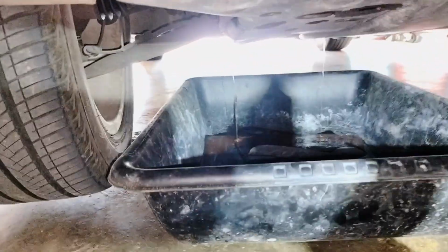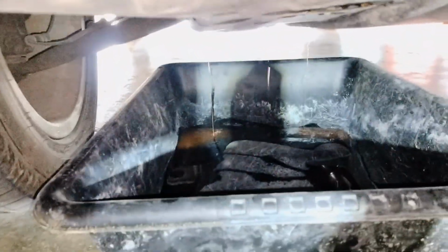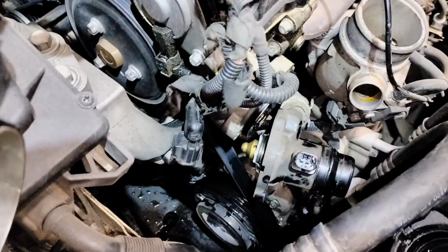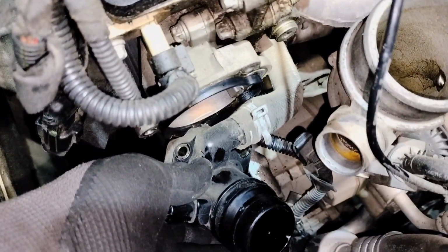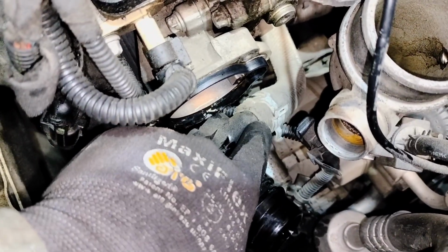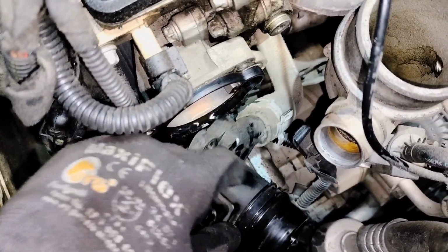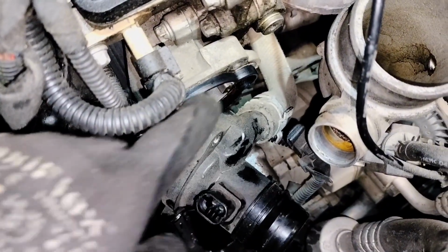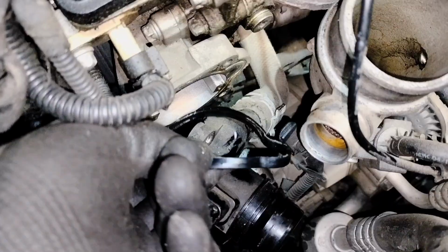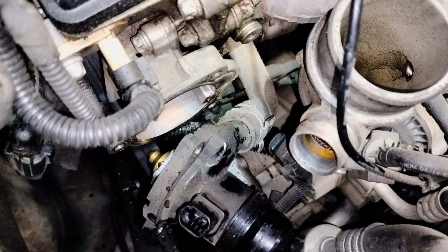So you definitely want a catch pan, because for example this one is catching a lot of coolant on the bottom. So now that I have it removed from the place, I'm gonna have to use pliers to remove that clamp. And I'm gonna just remove it, put it down, and kind of wiggle, and then get this thermostat out. And there's the gasket. Don't forget, this gasket does not belong in there anymore. Your new thermostat comes with the new gasket.